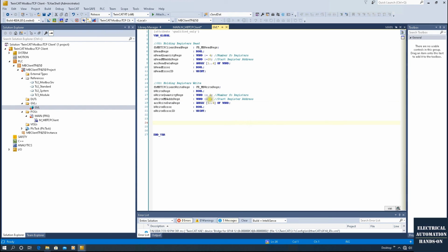So that means from the Modbus address 1, 2, 3, 4, the top 4 we are using to write the register. To read the Modbus TCP data, we will read starting from Modbus address 20 and the length is 4. So this is our target here. Okay, all right. So we created all those variables.